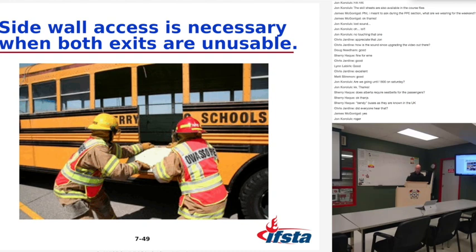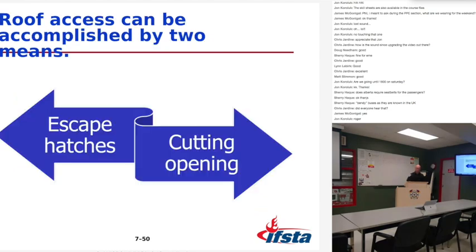The best tool for creating a large hole is a reciprocating saw with a 6-inch metal cutting blade. An alternate method would be remove the entire sheets of metal by popping rivets or welds with an air chisel. That usually leaves those beams, so you'd still have to cut those beams. And it says to only use as a last resort due to slow speed and noise.